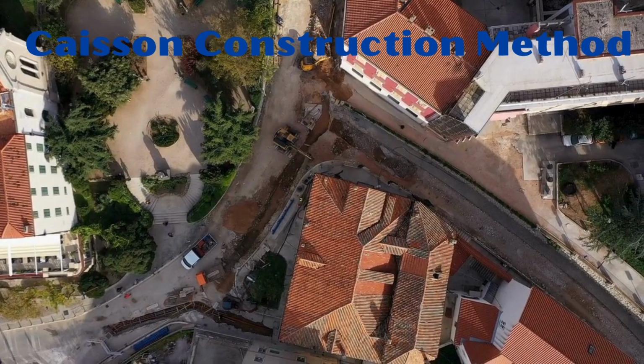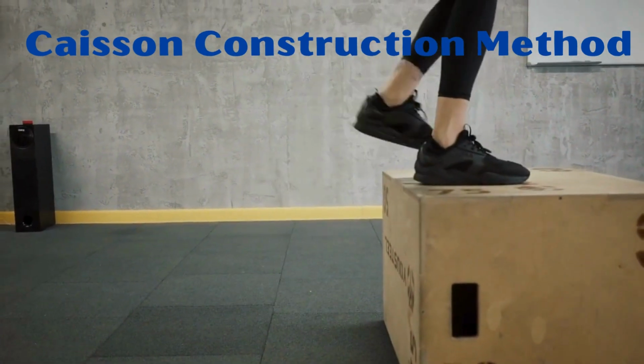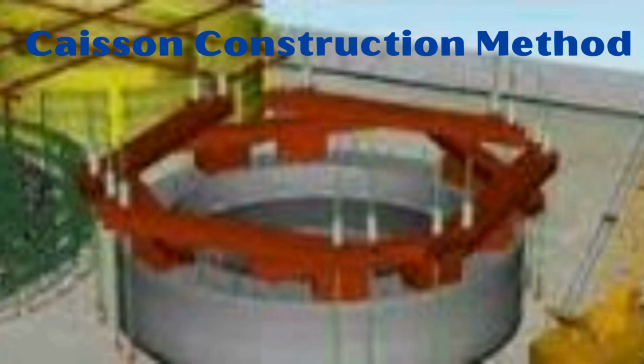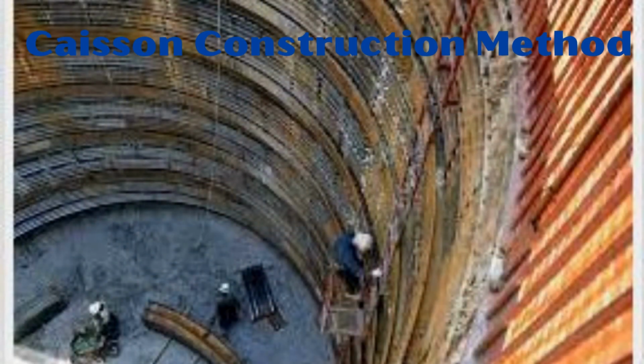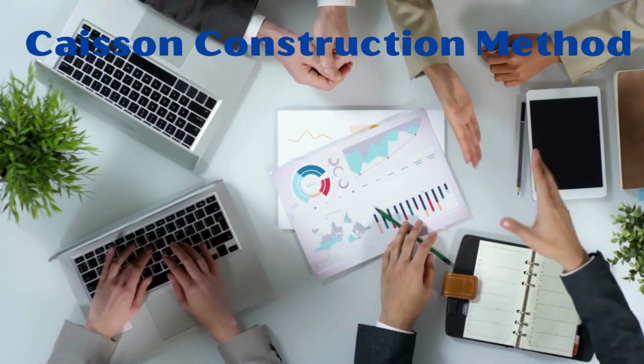5. Excavation and removal. Description: continuously remove soil from inside the caisson until the desired depth is reached. Importance: stabilizes the caisson and prepares it for the next steps. 6. Filling with concrete. Description: once at the desired depth, fill the caisson with concrete to create a solid foundation. Importance: provides long-term stability and strength. 7. Final adjustments. Description: ensure the caisson is level and correctly positioned before finalizing the construction. Importance: ensures the foundation meets all structural requirements.